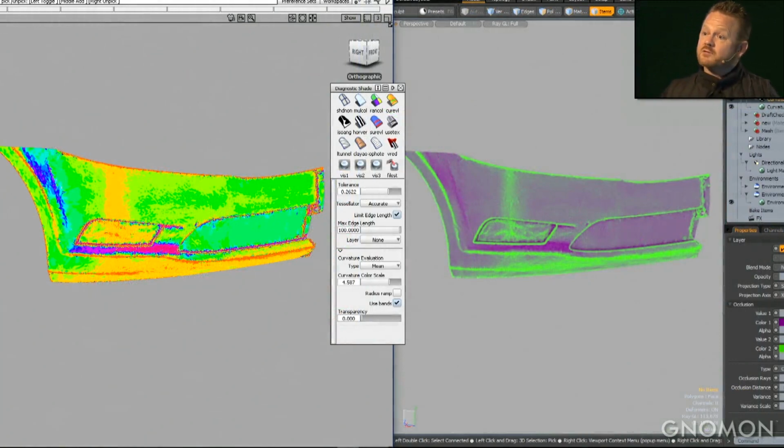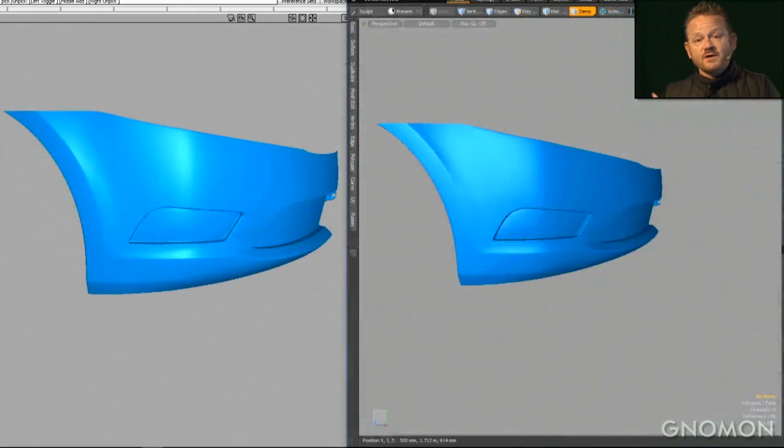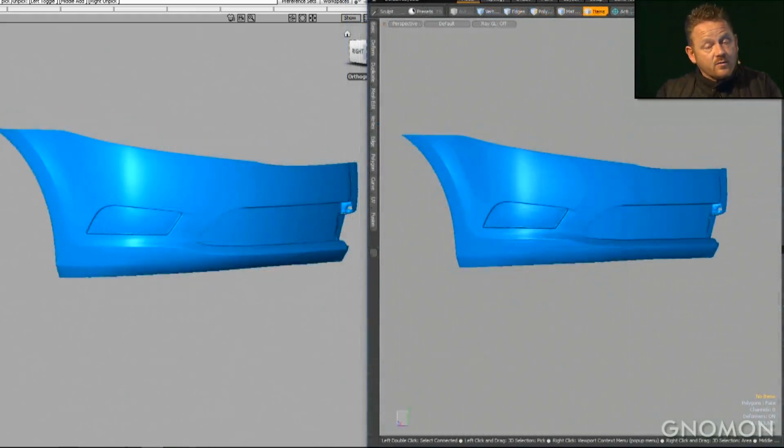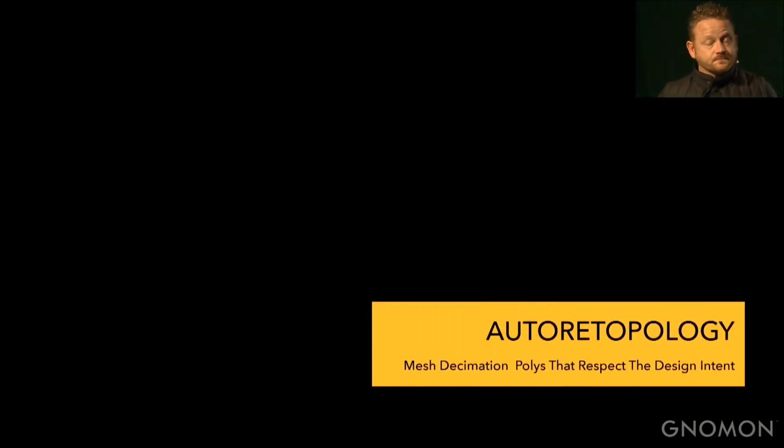In addition to that, being able to see curvature, continuity, and the convex and concave surface development allows you to develop your primary and secondary surfaces for when it's handed off to CAD modelers who need to spend a lot of time making it manufacturable. And also to be able to flatten out the perspective on a camera, Modo was able to do that.